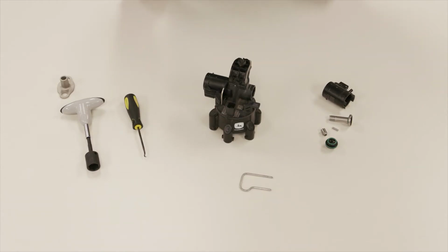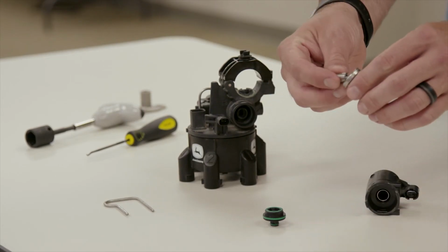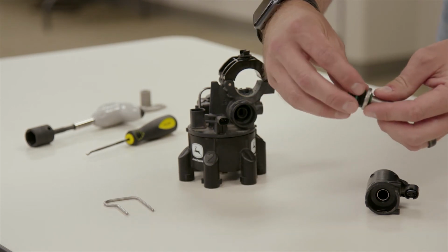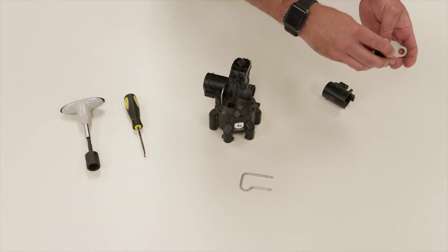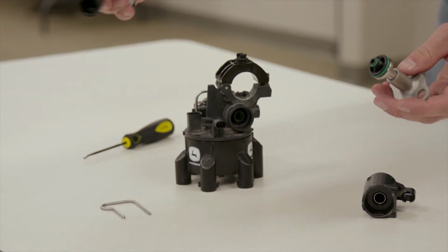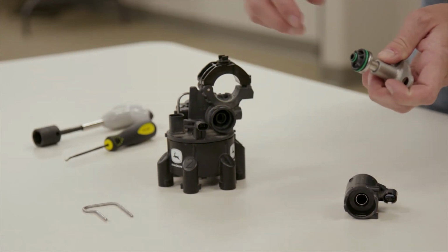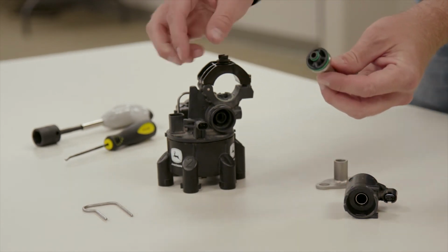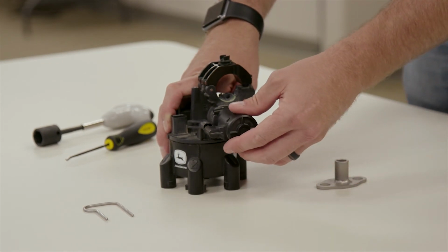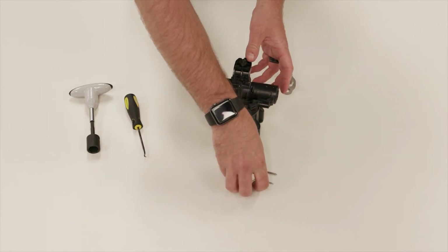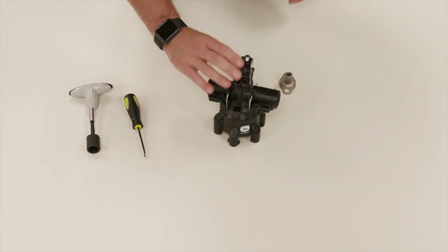To reassemble our ExactApply PWM system, we're first going to take our spring and our poppet and insert them back into the valve stem body. Those components need to go in first. Replace our black cap, ensuring that it is positioned correctly, and use our torque wrench to torque it to 1 click. We can then take our stem, reinsert it into the ExactApply nozzle body, and replace our coil pack. When fully inserted, we put back the retainer clip, and our reassembly of the ExactApply system is complete.